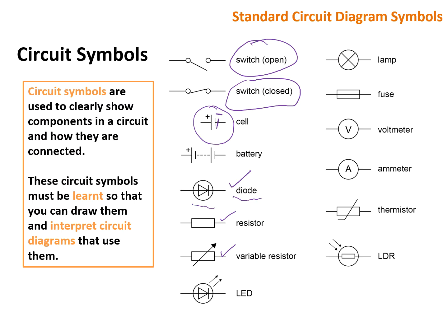At the same time, this symbol is a thermistor, so again a rectangle, so it's a type of resistor, but it depends upon temperature. And then this one, again, it's a rectangle down here, but it's a light dependent resistor. Ammeter's fairly easy, voltmeter's fairly easy. The fuse just has a rectangle with a wire going through the middle, and most people will recall what the lamp looks like.